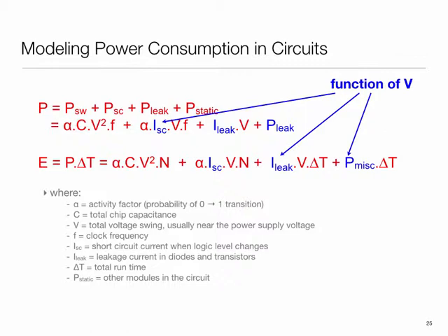Essentially, the key components are, first, power consumption which happens because computation is taking place or some activity is taking place. So the clock is running and bits are switching. If we stop the clock, or if we don't do any computation, as in keep feeding the same data values so they are not changing, then this power consumption would be zero. In one case, alpha would be zero, in another case, f would be zero. I can also shut off the power, so voltage can be made zero. C obviously is a function of the hardware, so you cannot affect that.